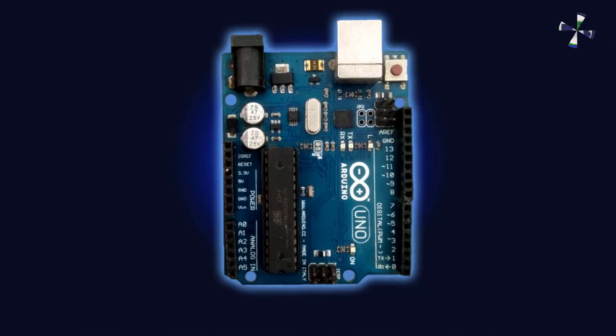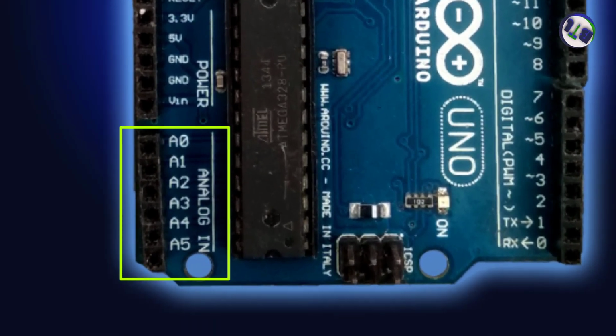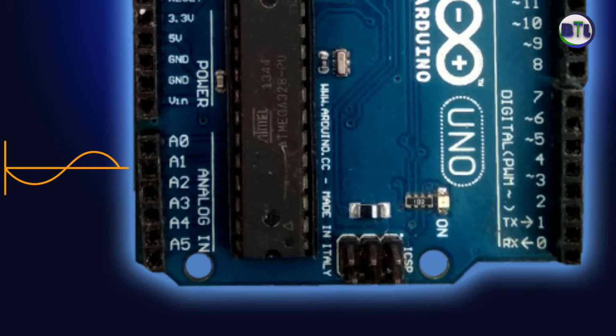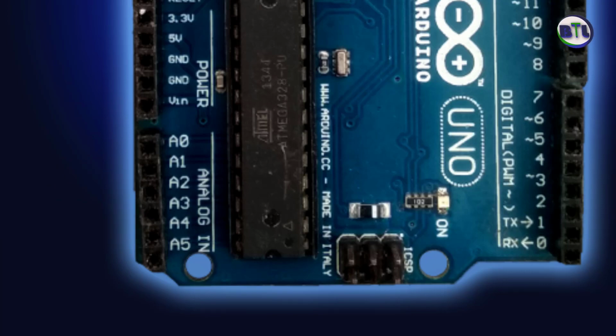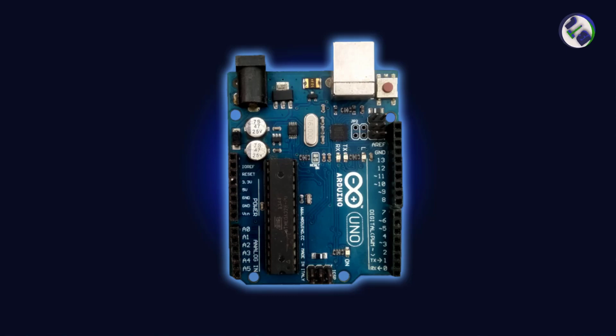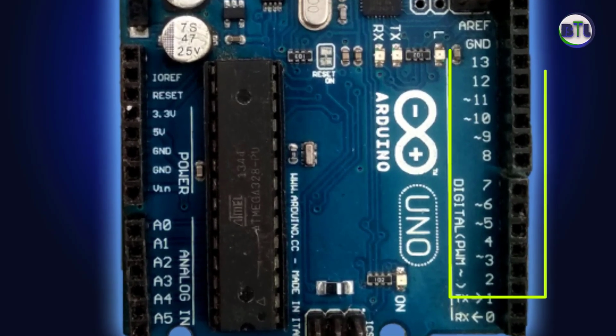Analog pins A0 to A5. Analog pins read continuous voltages from 0 to 5 volts, but not the current, as they have very high internal resistance, which allows only a very small amount of current to flow. They can also be used for digital inputs and outputs. Digital pins 2 to 13 can be used as digital input or output pins.